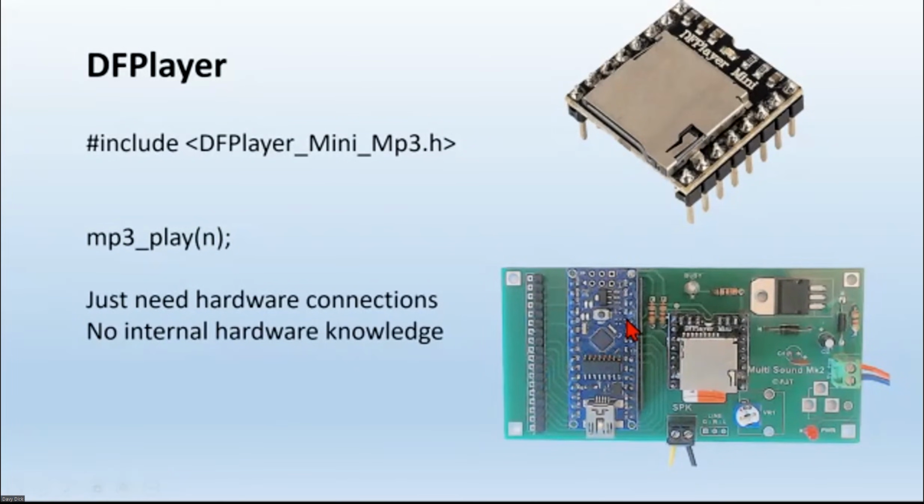And then all you have to do is connect the various pins on your Arduino to the pins in the DFPlayer. And the program can then sort it out. In this example, we've got a bunch of inputs, digital inputs. If you bring one low, that'll play track 1, that'll play track 2, that'll play track 3, track 4, etc. So it's a simple approach. And all we have to do to make all that work is to add in the word include the DFPlayer.